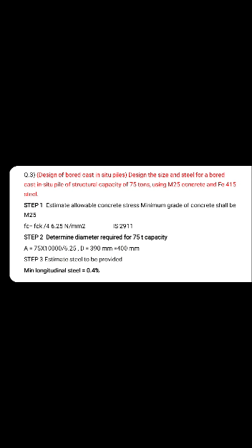Now the last problem of pile is design of bored cast in situ pile. Design the size and steel of a bored cast in situ pile of structural capacity of 75 ton using M25 concrete and Fe415 steel. First step, estimate allowable concrete stress.